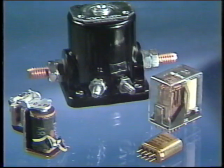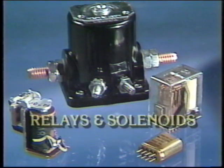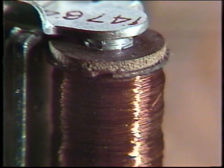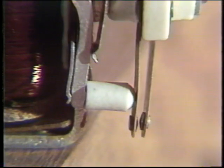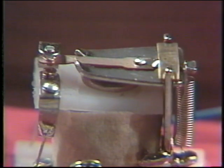Some switches are operated electrically and are divided into two categories: relays and solenoids. A relay is an electrically operated switch with a fixed iron core or no core at all. It is simply a coil of wire that, when operated, creates a magnetic field which pulls on a set of contacts to either open or close a circuit or several circuits.